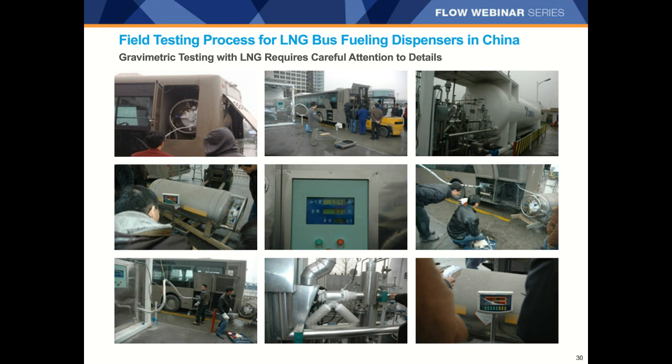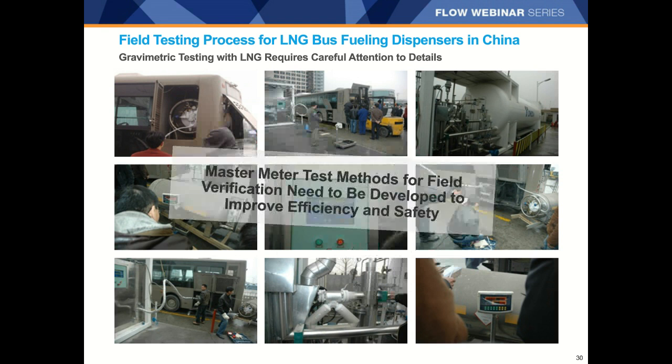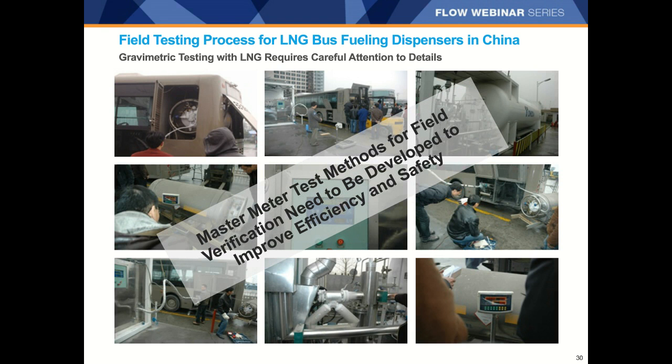Many operators use portable weigh scales and fuel storage tanks to perform this type of field testing today. However, this process can be rather involved and might be subject to difficulties as the weather, wind, and other ambient conditions choose not to cooperate. A better alternative for field testing of LNG transfer systems that would be right in line with the bootstrap approach that VSL is using for the mid-scale facility would be portable master meters.